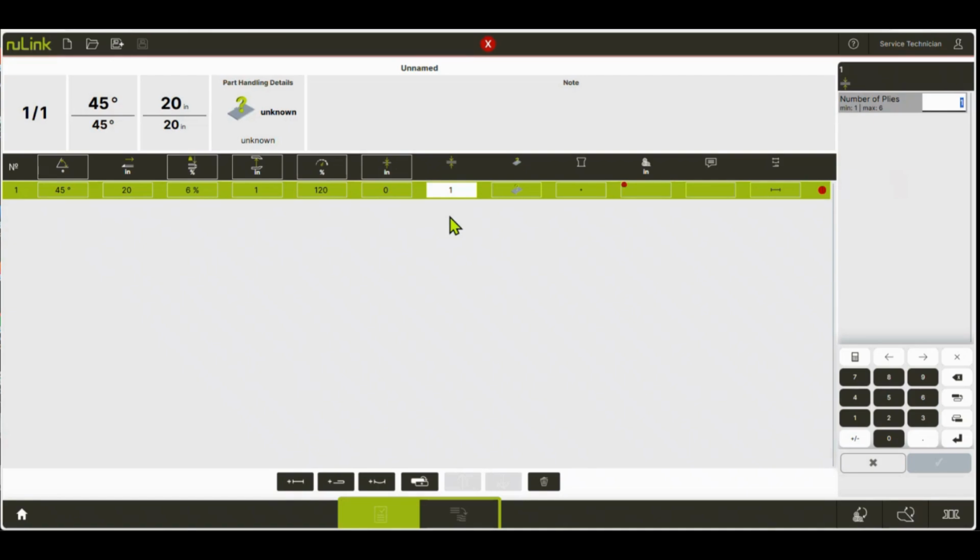They don't have hems on the end. All they got is a little pitch angle in the middle, right? And I'm running 29 gauge, and I know I can stack up 3 or 4 of these things and bend them all at one time, right? And I put them in the machine and I clamp down on it. But if the machine is only expecting to see a thickness of 1 of those, and it sees 4 of these things, it's going to give you an alarm, say, hey, your material is too thick.